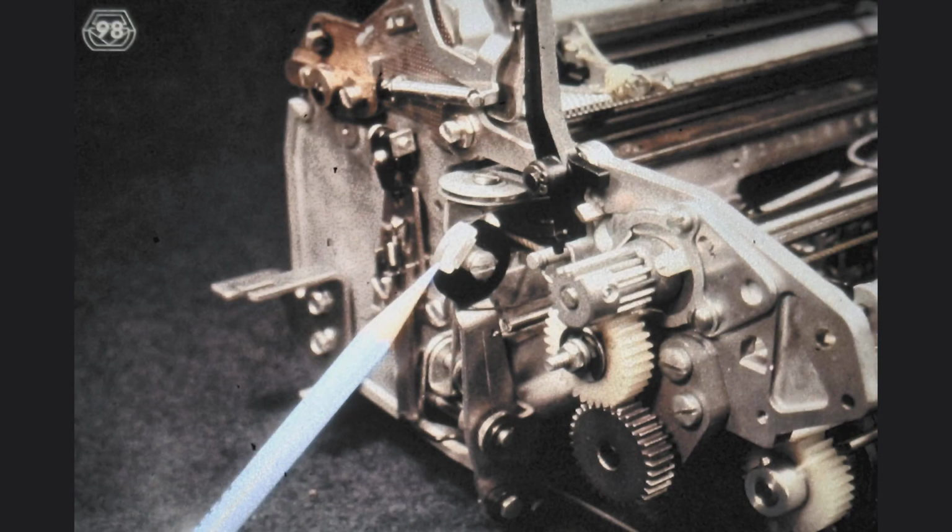The indicated shoe over the pulley on the rotate arm has the purpose of preventing the rotate tape from accidentally jumping off. This shoe does such a good job that in order to remove the rotate tape, we must loosen the screw and pull the shoe away from the pulley by approximately 3 millimeters. As you loosen it, notice the angle it occupies on the rotate arm. It should be at approximately 150 degrees when viewed from the front of the machine. Be sure to place it into the same position again during reassembly.